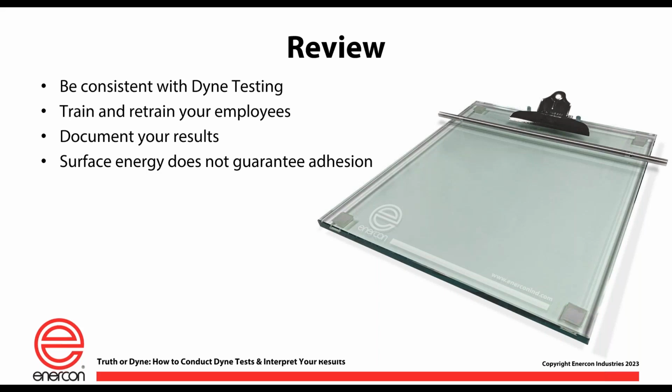A quick review here before we get to your questions. Some of the highlights and must-haves. Make sure you're consistent with your Dyne testing. Make sure that you are training and retraining your employees as needed to do them consistently and properly. Always document your results, and probably add in here, don't get too concerned on a difference of a couple of Dynes.